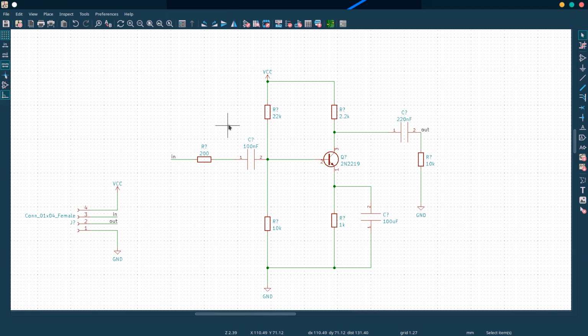But it's kind of a game of cat and mouse, because you'll say, I need this value of capacitor, and then you look it up and find it's only available in certain sizes, so can I use a slightly different capacitor with a shape that fits my board better? Or I found that 350 ohm resistors don't exist, or they're like $30 each because they're so non-standard, but 347 ohm resistors are super standard, 10 cents each. Super weird, but that's just how it is. Make concessions where you can.